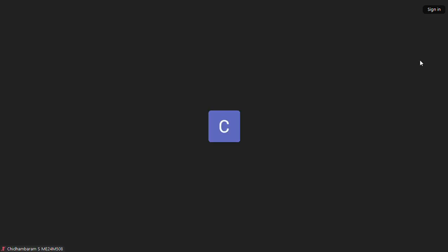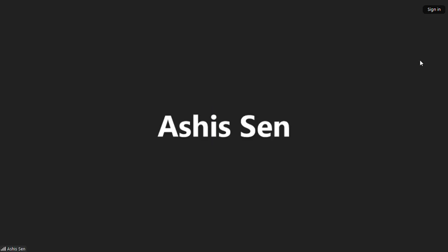I was talking from the point of view of doing experiments in a lab, where you can very well put your reference junction at a fixed temperature. But that is not possible in an actual machine. So there you have to use the differential thermocouple. Sure, sir. Thank you.